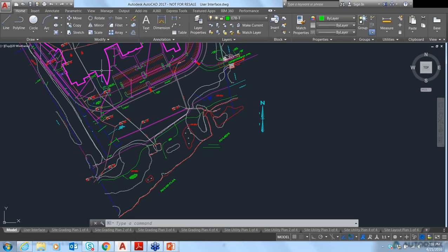Now, for those of you who are newer to AutoCAD, you have the ability to set the number of seconds before that second or third layer of information displays. So if you're newer, you might want to set the number of seconds to 0. So as soon as you hover over that command, that information is going to immediately display. But if you're a more experienced user, you might want to set that number of seconds to 2 or 3 so that you have that time lag. And when you go ahead and hover over this, it's not all going to display at once.